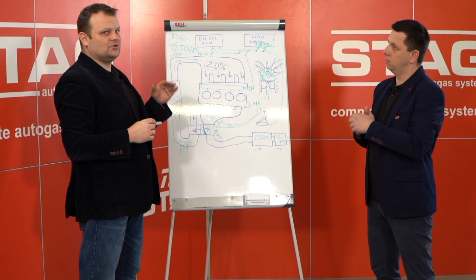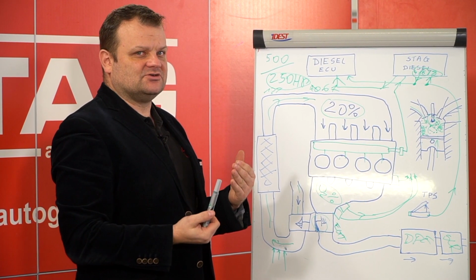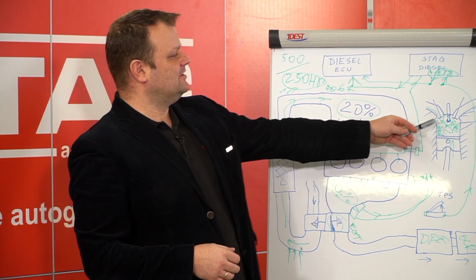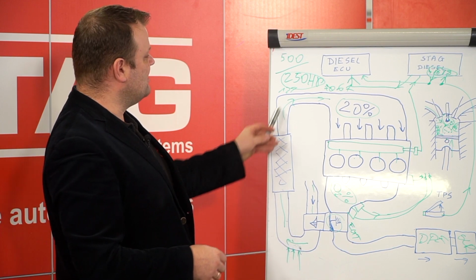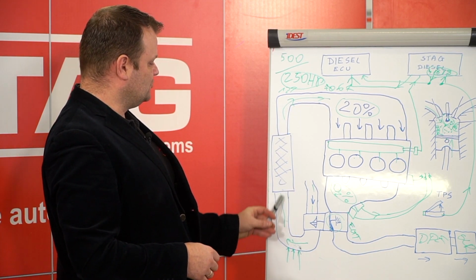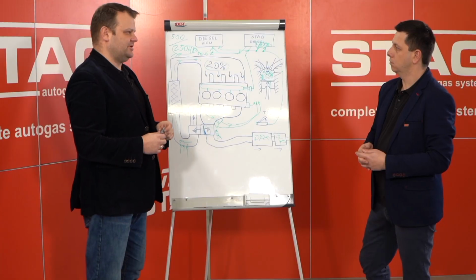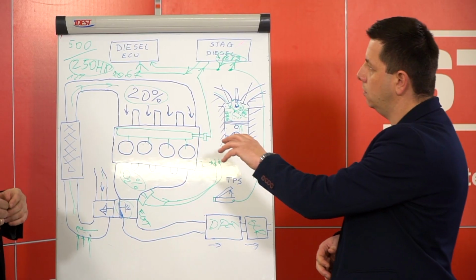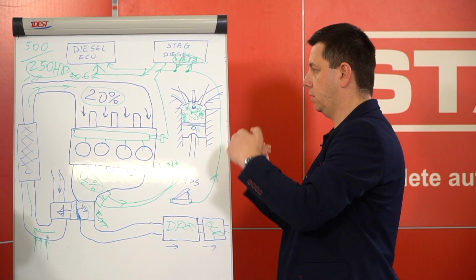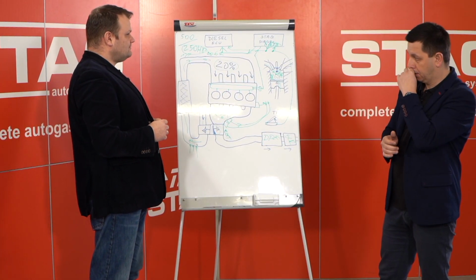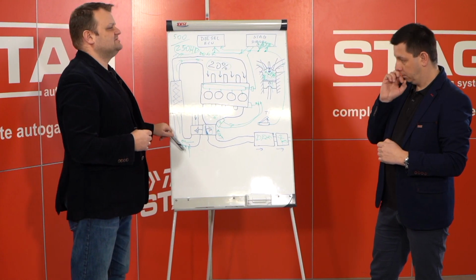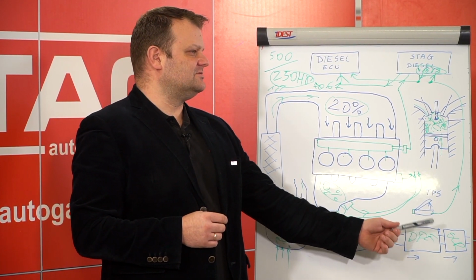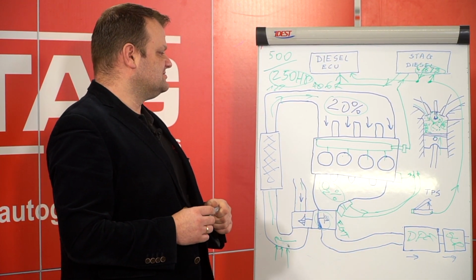This is the limitation. If knocking is occurring, we need to reduce the gas doses, and then, of course, the efficiency is going lower. So to prevent it, we need to have a long enough trip for the gas together with the air to mix properly. So if you install injectors far away from the admission, you will have less knocking. Exactly, and less NOx. That's right. So we have the power factor, and we have the place to put the injectors to prevent knocking and to protect the DPF and SCR systems.